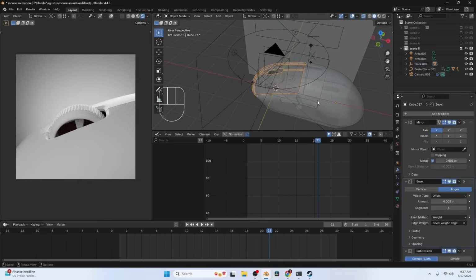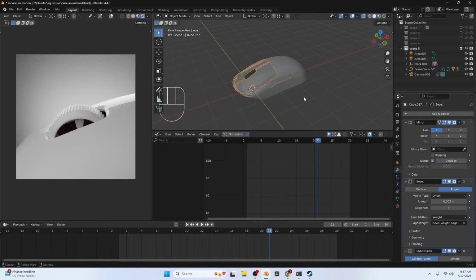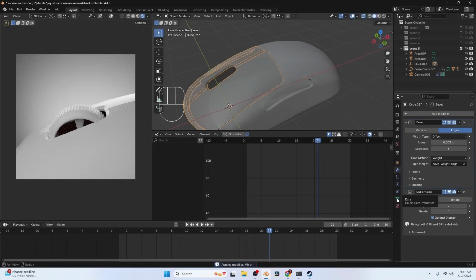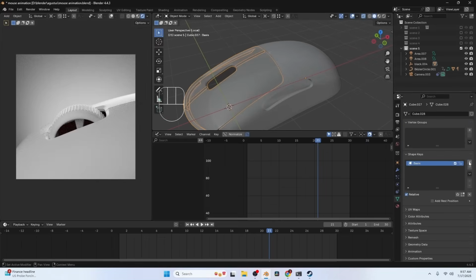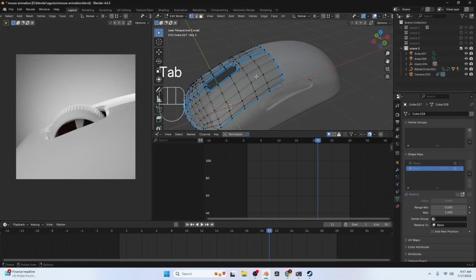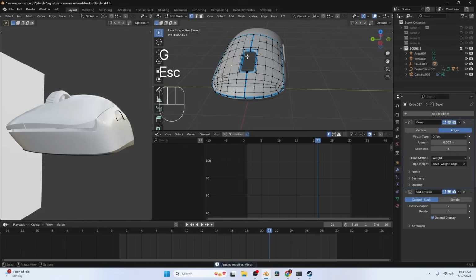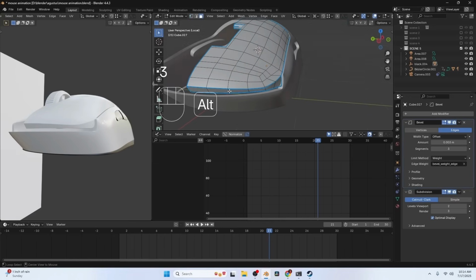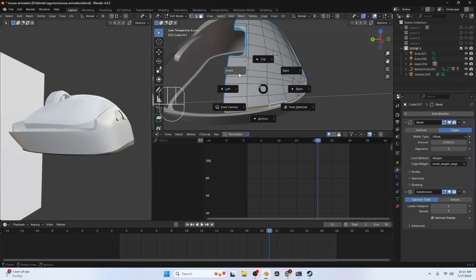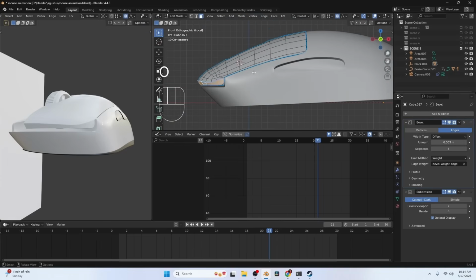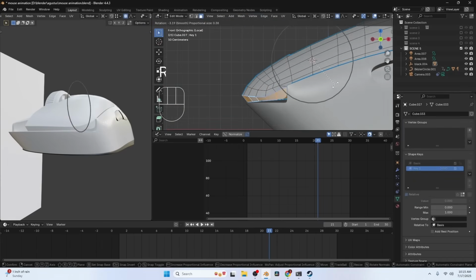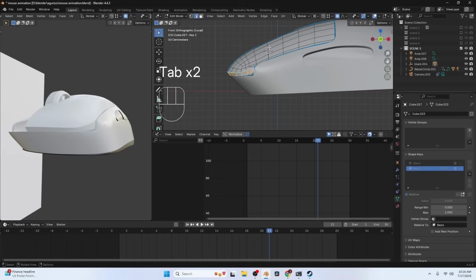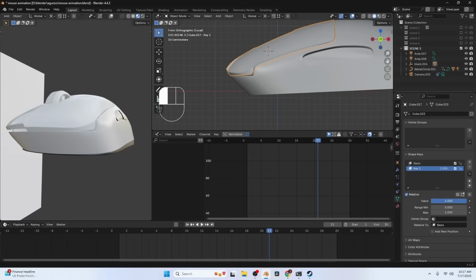In this case, I'm going to select these two objects, just press slash. Mirror of this object, apply. Object data property, shape key, click here, then add another one. Tab to edit mode, select one of these, press L, H to hide. Then select all of these vertices, press Shift S, cursor to selected, press 3 to change to face mode, click like this, all of this. Go to the front view, press O to enable proportional editing, press R, rotate like this. Back to object mode, when we increase the value, this will happen.